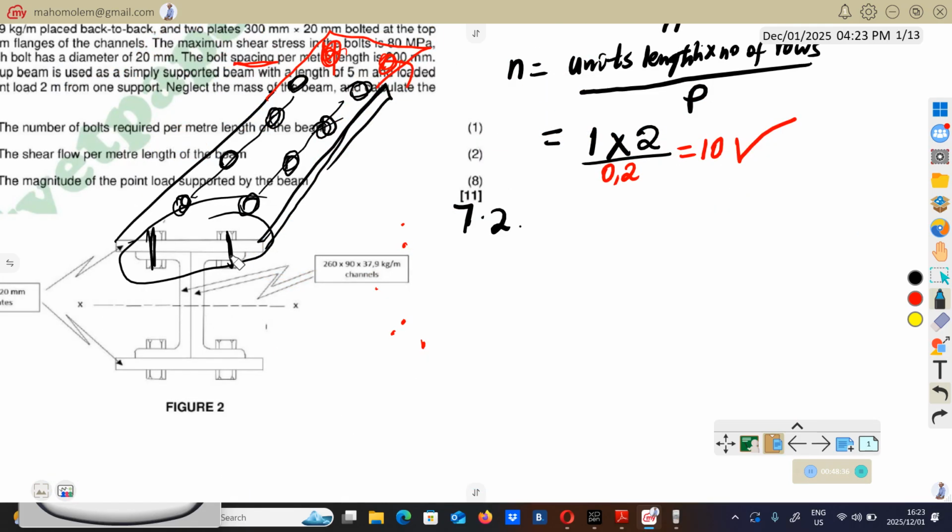When we check our sketch here, we only have 2 blades. If we have 2 blades like this, the shearing will only occur here. Normally double shear we have when we've got 3 blades, or when we have a clevis bolt. From science 4, you will recall that we used to have something like this.